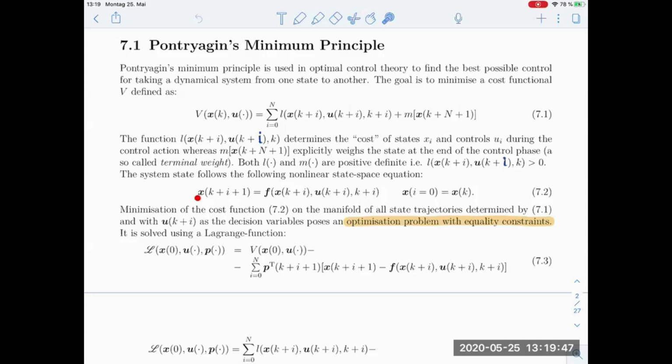So we will have equality constraints in this fashion here. We will have, for each time step in the horizon, up to this time level k plus n plus 1 on the left-hand side, these equality constraints, which means that the next state in our time horizon is some function of the current state, the current input, and maybe time itself, if you want. So that's a very general definition. It actually supports nonlinear dynamics here. F could be a nonlinear function of x and u.